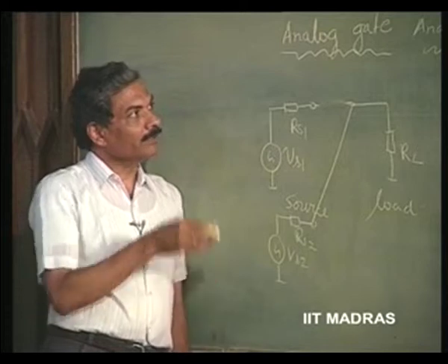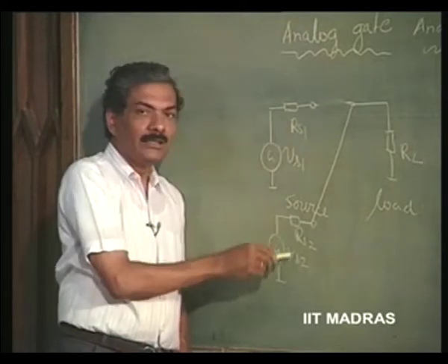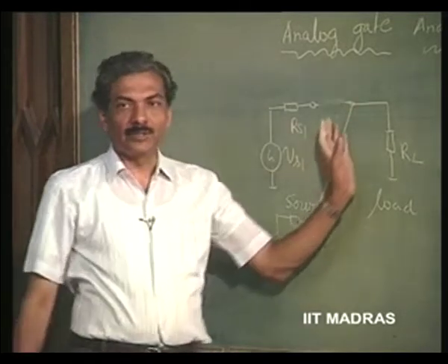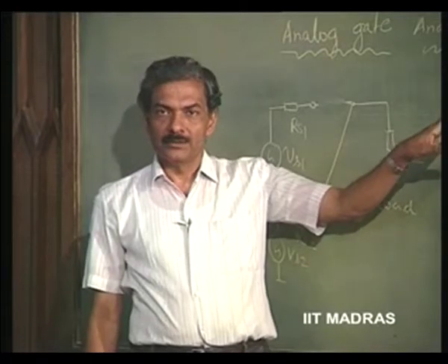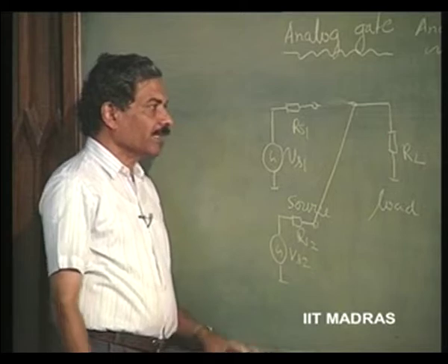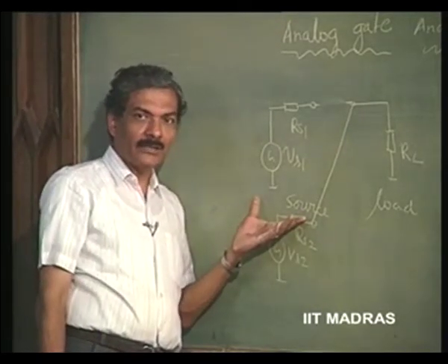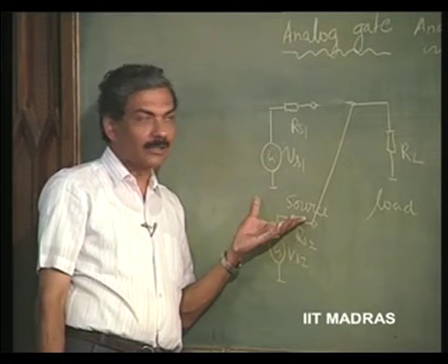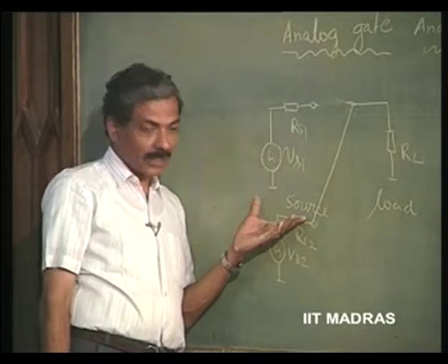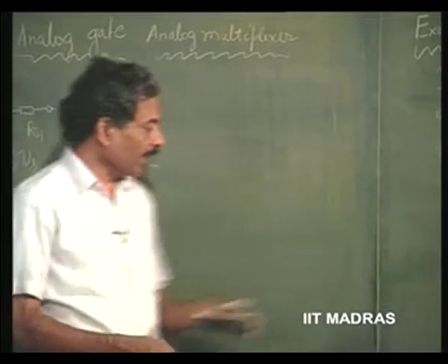That requires first an analog multiplexer, which will sample these different analog signals, and later on this data is going to be maybe digitized, appropriately. So, that is a different aspect, but the front end circuit for any such operation of data logging is what is called an analog multiplexer. And we are now going to discuss how an analog multiplexer can be designed.